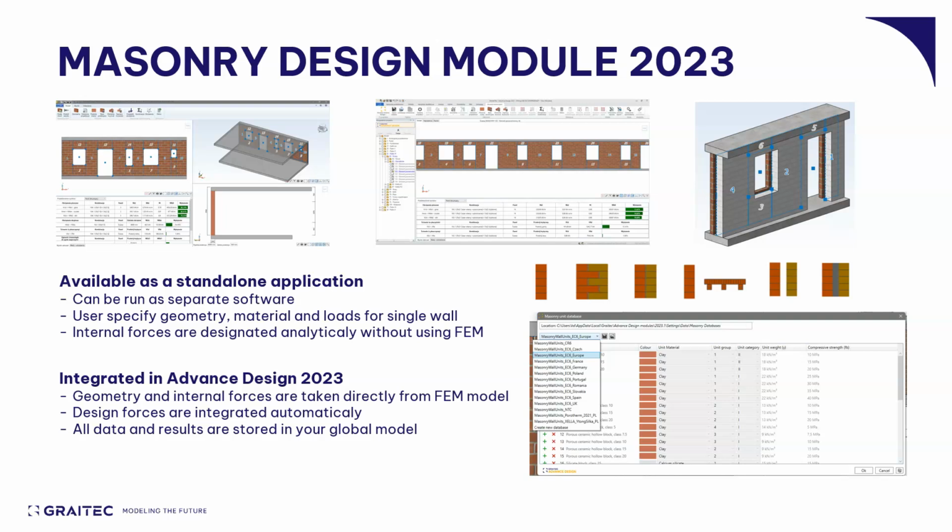What's most important is that you don't design a single particular panel at once, but you design a whole wall that consists of many panels which were defined by the openings within your wall. Also, we perform any checks that are requested by Eurocode or any other standard that was implemented. So vertical loading, shear loading, bending, stresses, and so on.